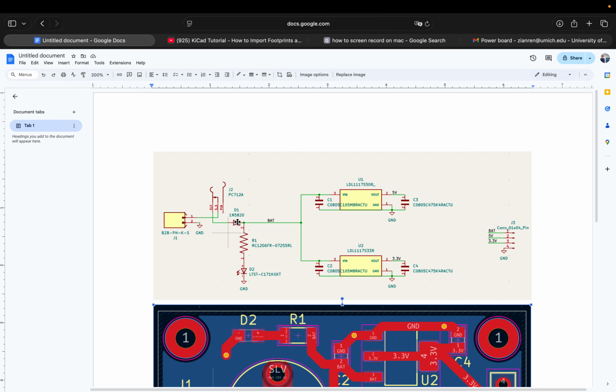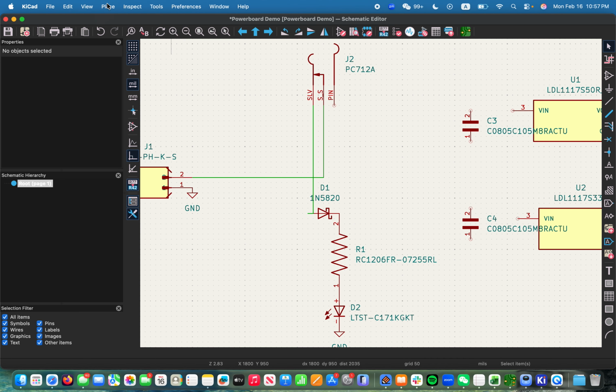And the next thing we need to do is from the diode, which is our battery power line. We will name it battery later. So that is net labels. We will talk about that in a little bit here. And then we will go to the 5-volt LDO and the 3-volt LDO. So the same thing, we go to place, wires, go to the right side of this diode, go up here, click once to kind of make sure that it stays on that point, and then click to 3.